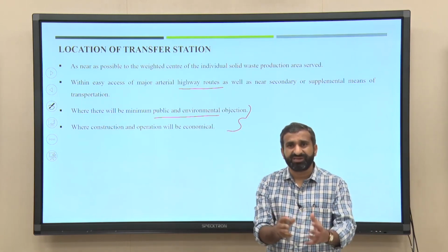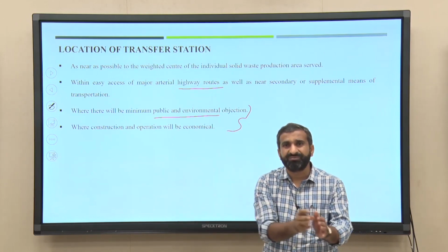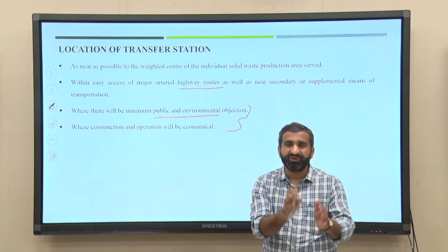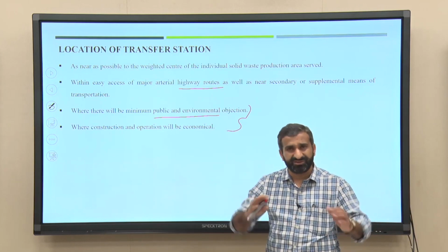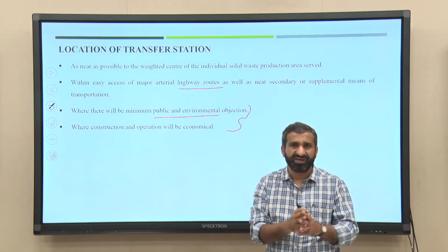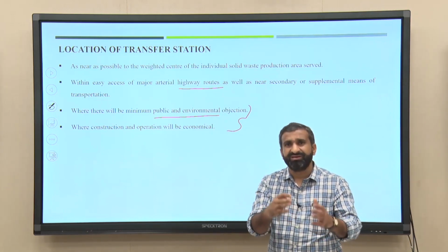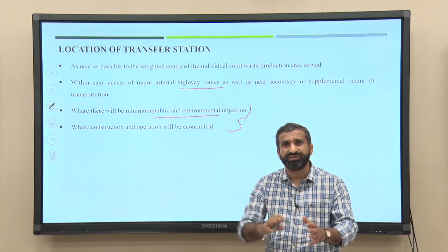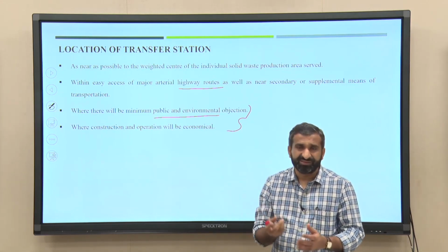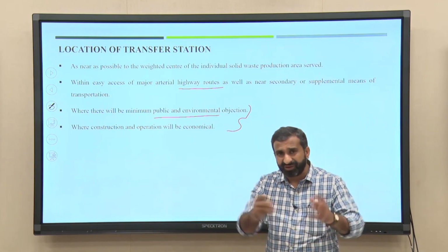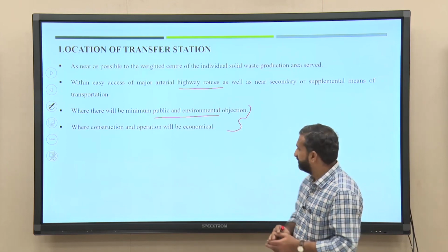So, when you are planning for a transfer station, you need to be ready with proper primary collection and proper secondary collection. Now, if you are planning for a transfer station without any recycling facility, I think that will not be economical, because to make the transfer station economical, you also need to see how best we can recycle the recyclable matter. So, I think a lot of issues have to be discussed before planning for a transfer station.